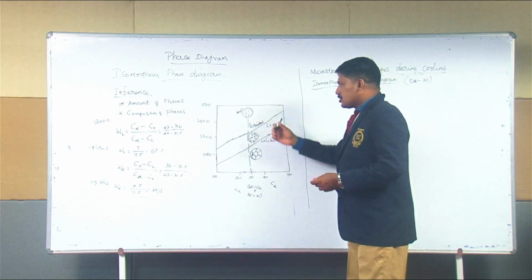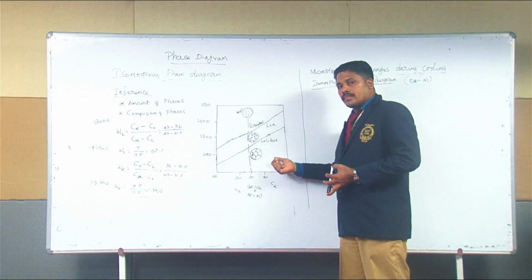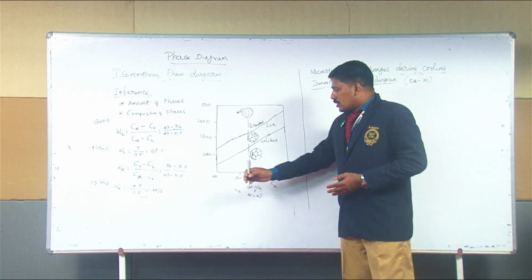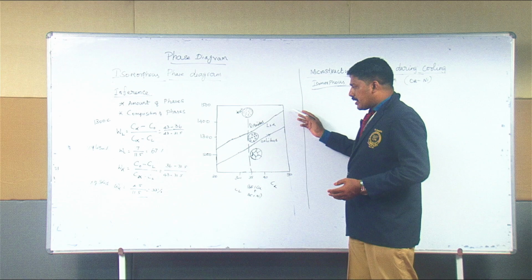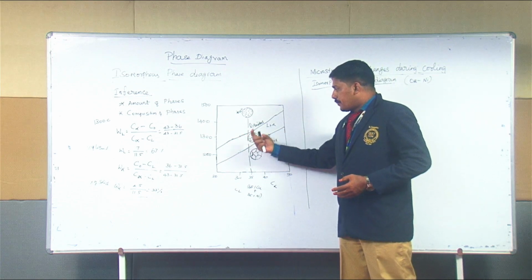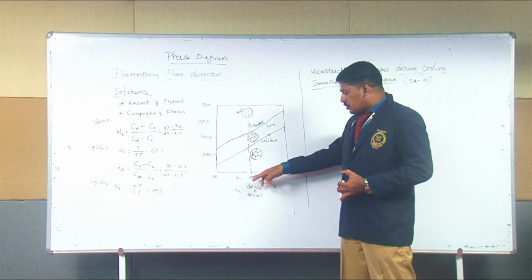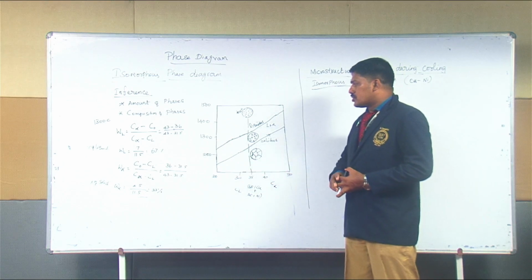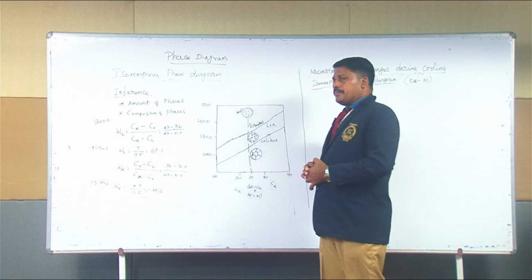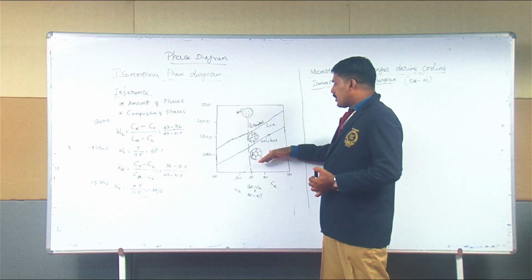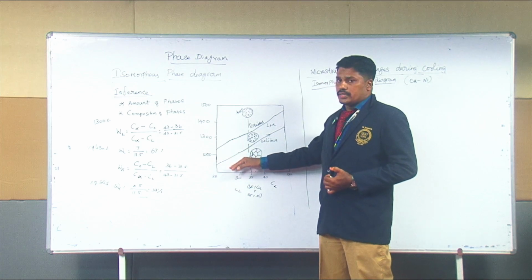For example, this is a magnified region within the copper-nickel phase diagram. When we change the composition, the melting point temperature is slowly raised, and the width of the two-phase region also increases due to the different composition. The isomorphous phase diagram has three different phases: liquid, the two-phase region, and solid.